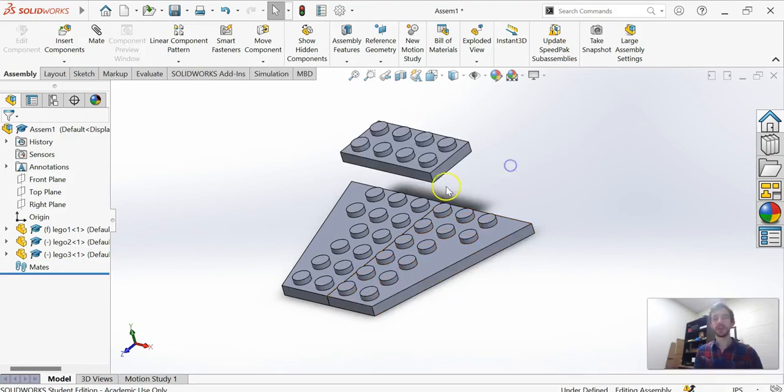There we go. Now let's try two points. Well, I'm not going to do two points, but with two points, they are now connected forever. They can never move. And I can do the same thing with a point and a line. It means that this point will be on this line forever. It'll be on this little section forever, or rather, somewhere on this infinitely long line that would go through that line.